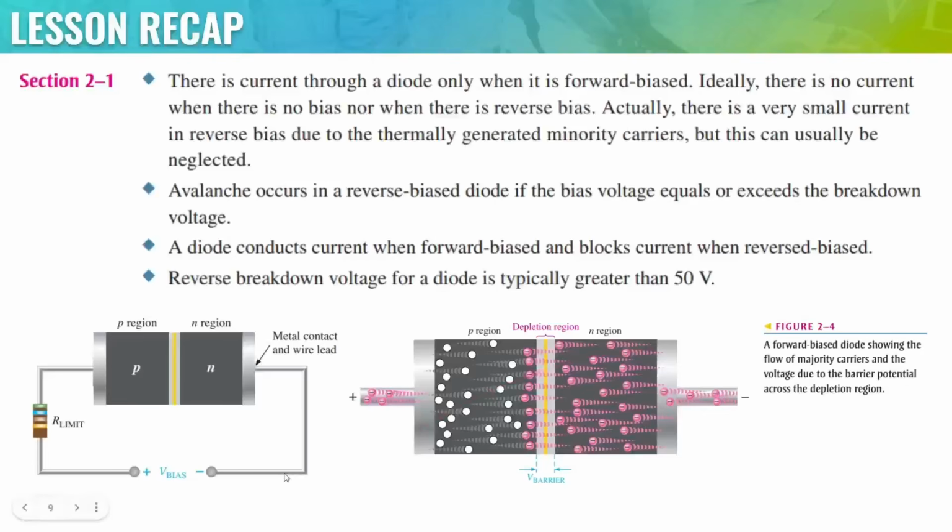Just to add on, even if this is the direction that we are going, a high enough voltage, especially from an AC source, can cause the diode to conduct the current in the wrong direction. That's why we typically compute for the voltage. We have to make sure that it is within the normal operating limits.